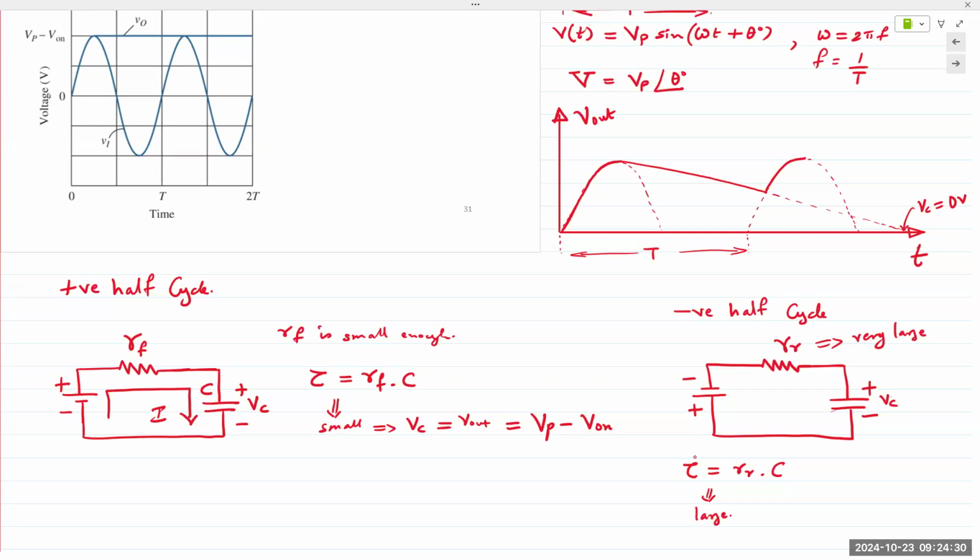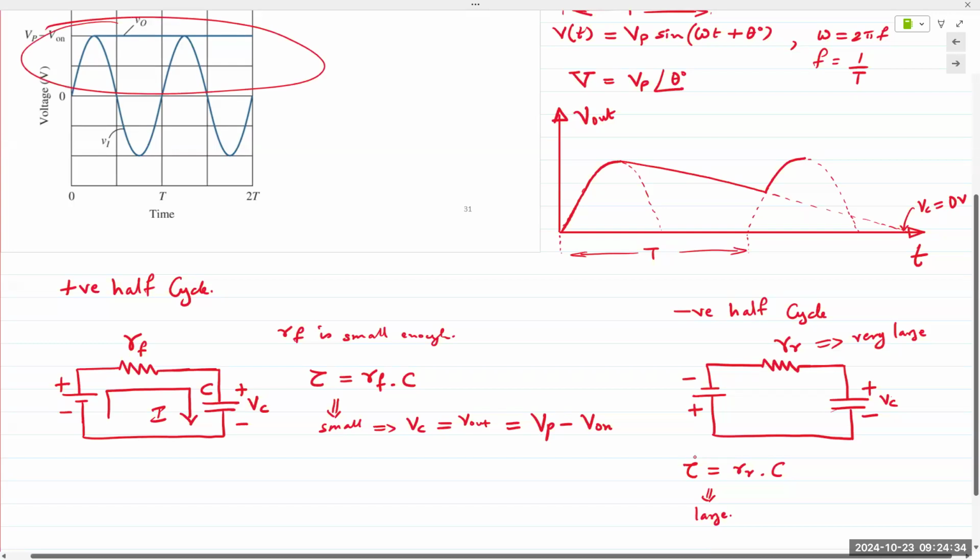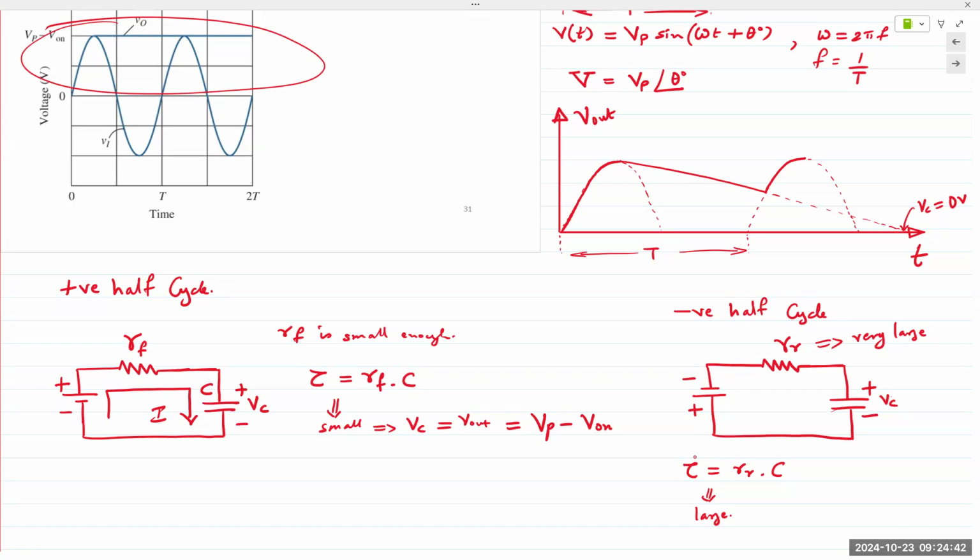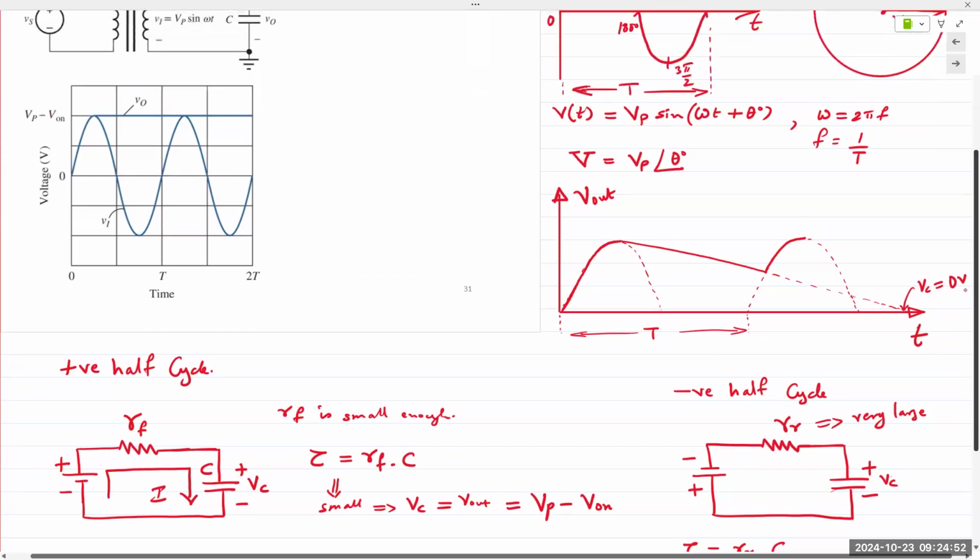What is shown in the waveform on the left, right here at the top, is an ideal capacitor, an ideal diode. So an ideal diode behaves like an open circuit. Ideal capacitor will hold its charge indefinitely. And so V out across the capacitor is simply a flat line. So again, this is an ideal circuit up on the left.